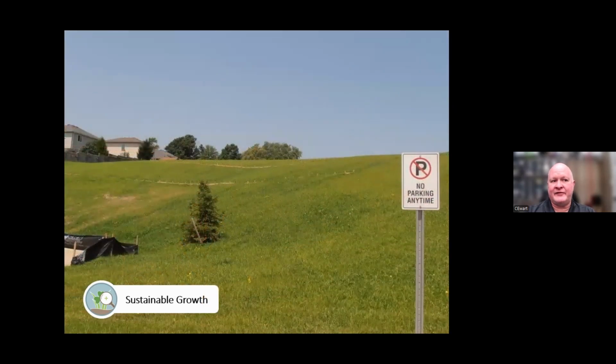This was the end result after the reapplication. And it was a fairly successful reinstallation. Interesting thing on this one was soil testing was done on this before the initial, and amendments were put in. But the unfortunate thing was that the design, the lack of slope interruption, was where the major problem was lying.